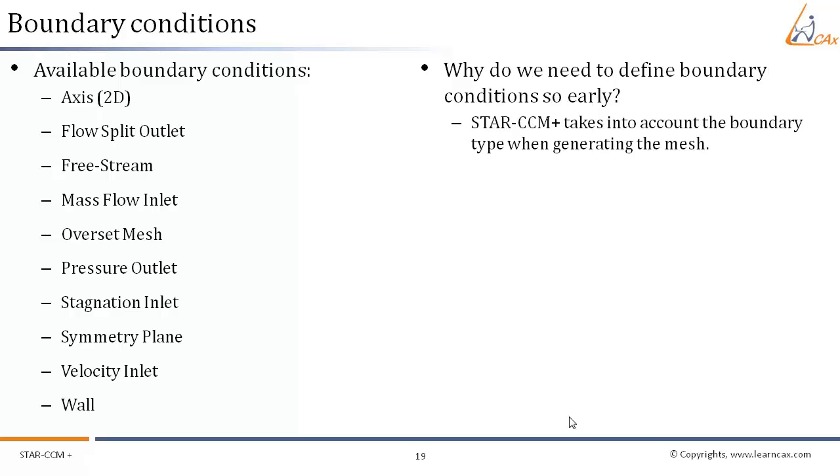Why do we need to define boundary conditions so early? This is because STAR CCM+ takes into account the boundary type when generating the mesh. Hence, the information of boundary conditions is needed even before mesh setup.